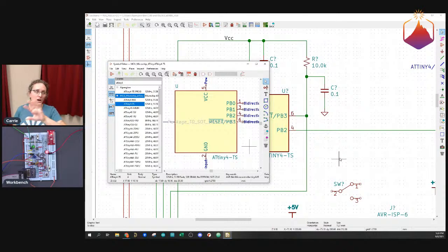We have all of the footprints for all of the parts where they'll eventually be soldered, and I'm going to connect the dots and draw lines in copper from one part to another. But because you have the schematic information linked to it, you can see that this leg on this part needs to be connected to this leg on that part. It makes it a lot easier, and there's error checking involved and all that sort of good stuff.